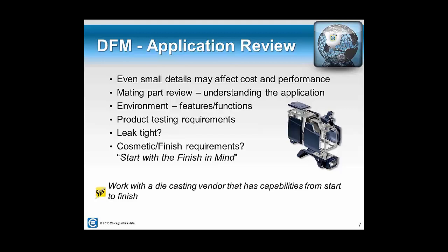Is your requirement that the die casting be leak tight? That is a fairly common thing that comes up, and we have additional questions and solutions that will help with that factor. For example, might the part need to be impregnated with an epoxy sealer to help seal up any areas that might tend to lead to leaking through?